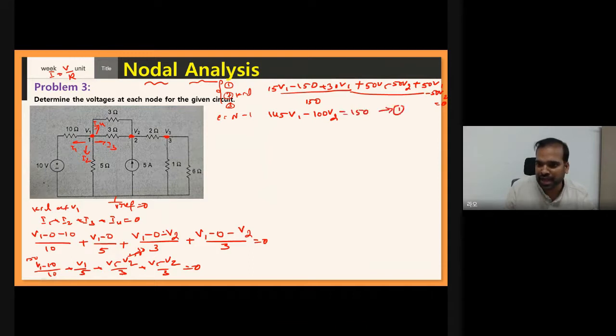Now, if you solve that above one, you get this is equation 1. Now, if I apply KCL at node V2, then before applying KCL at node V2, what should I do? I should consider current is leaving. I already considered until I4, this is I5, and here this is I6, and this is I7, and here this is I8. Now if I apply KCL at V2, I can write I5 plus I6 plus I7 plus I8 equal to 0. Clear.